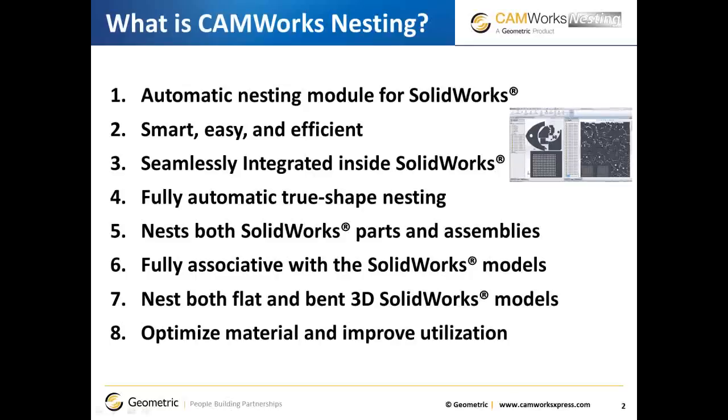CAMWorks Nesting is seamlessly integrated inside SolidWorks and automatically creates nested layouts as a SolidWorks assembly. CAMWorks Nesting uses the latest fully automatic True Shape nesting technology and helps you to create nested layouts of both your SolidWorks parts and assemblies. CAMWorks Nesting creates fully associative nested layouts, so if your part model changes, the change to the component will be instantly reflected in the assembly.